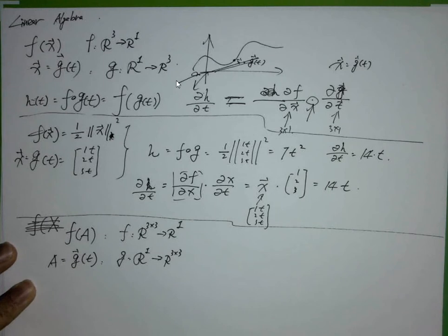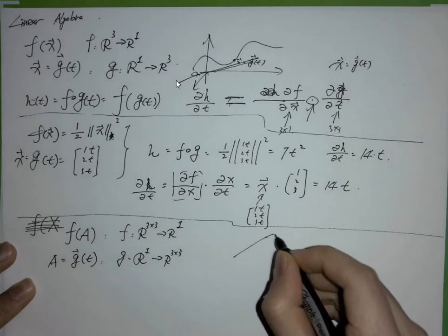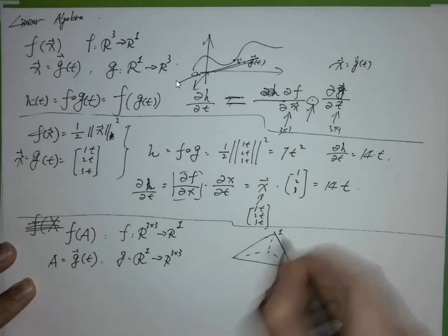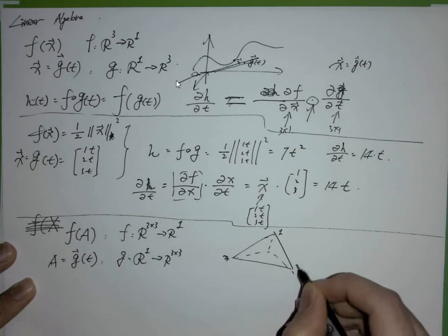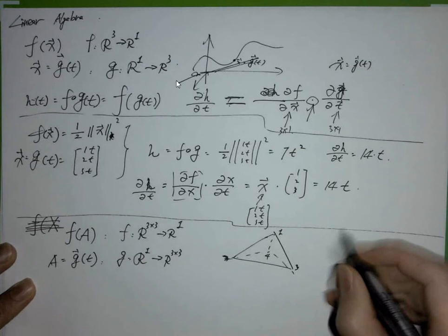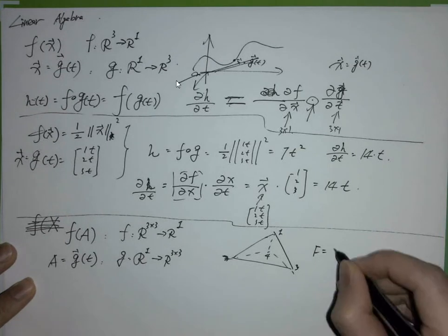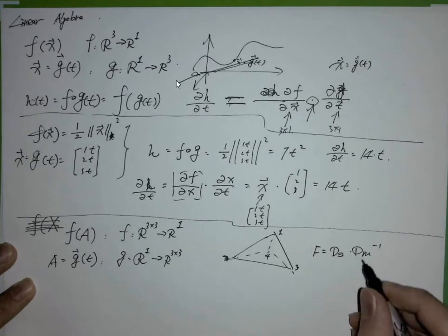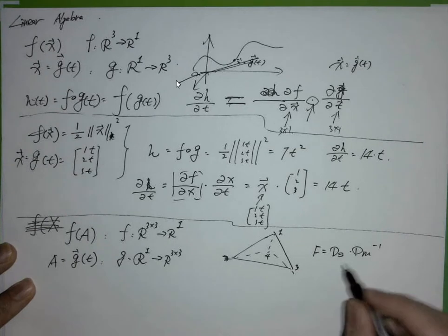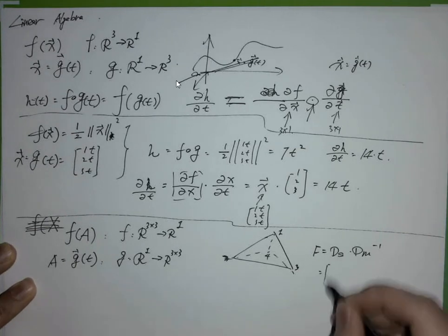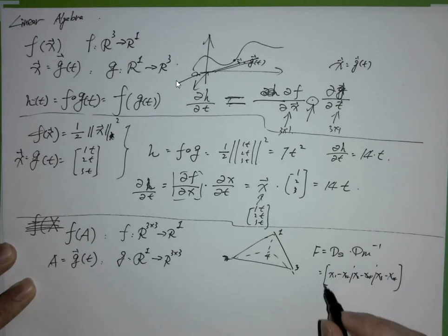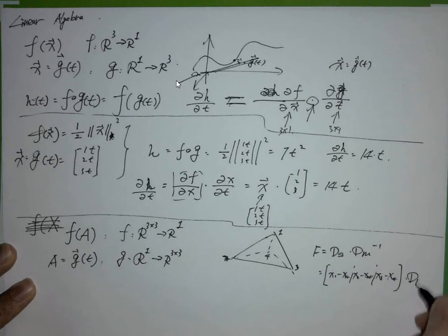And think about it. Think about our discretized case. If I have an element at four points, 1, 2, 3, and 4, we know that the deformation gradient F can be written down as something like Ds multiplied by Dm inverse, where Dm is the rest shape edge matrix and Ds is the current shape matrix. So Ds can be seen as x1 minus x4, x2 minus x4, x3 minus x4, and Dm is the same one, just applied on the rest pose. It's constant, Dm inverse, right?